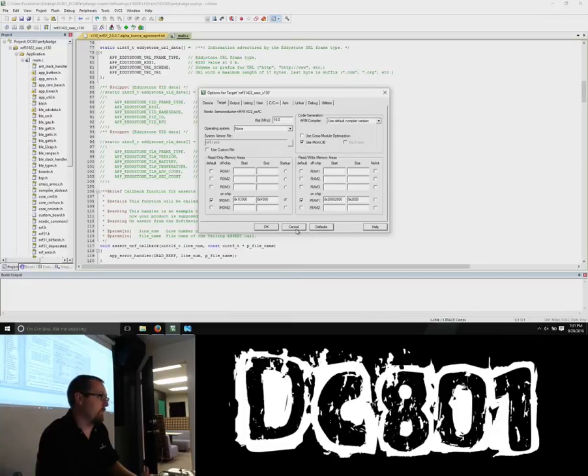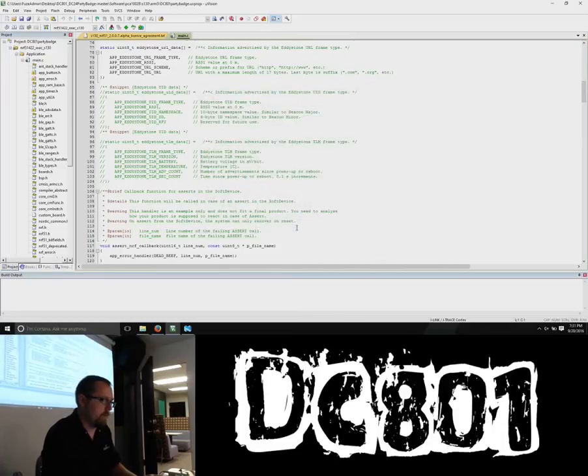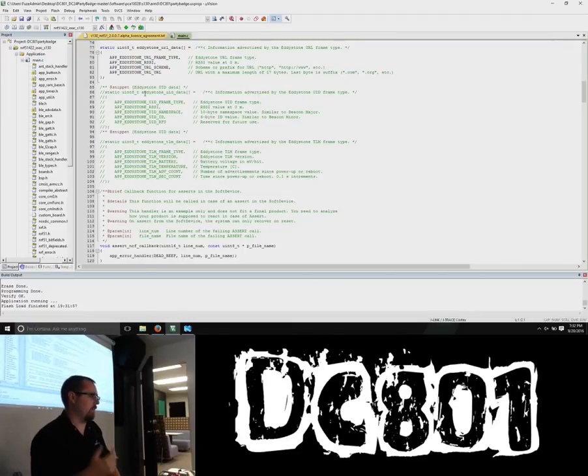We have 256 kilobytes of memory to play with on this device, which is kind of cool. And straight from Keil, once you have it programmed and set up, you just load, and it will load straight to the badge. And it programs it basically instantaneously. And you can debug through it, and you can program it in real time with this. And literally F5, recompile, and then reload, and it instantaneously overwrites the application layer.